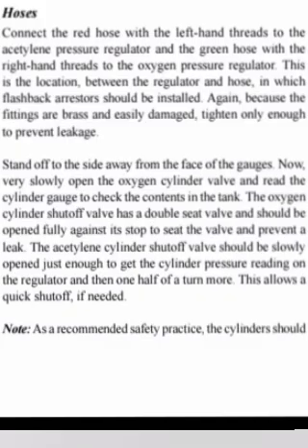Hoses. Connect the red hose with the left-hand threads to the acetylene pressure regulator and the green hose with the right-hand threads to the oxygen pressure regulator. This is the location between the regulator and hose in which flashback arresters should be installed. Again, because the fittings are brass and easily damaged, tighten only enough to prevent leakage.